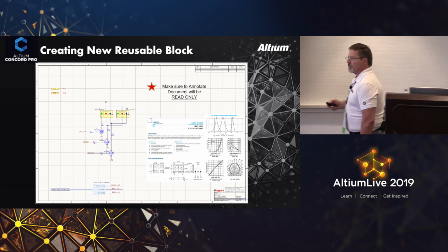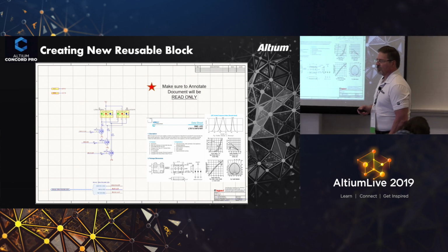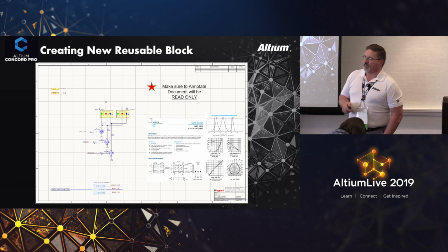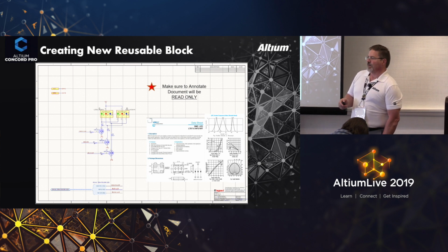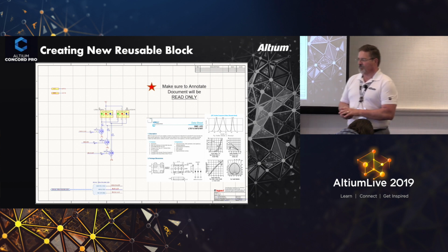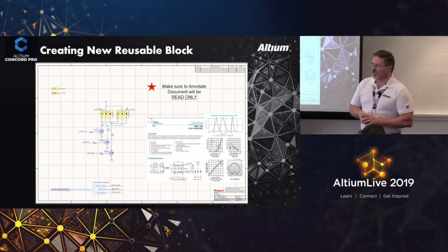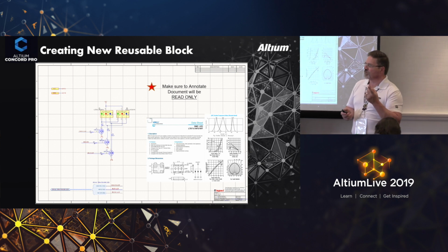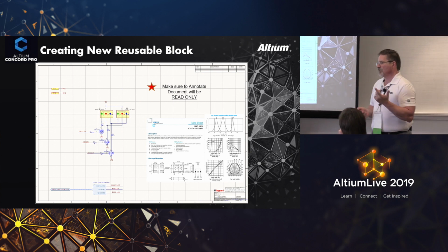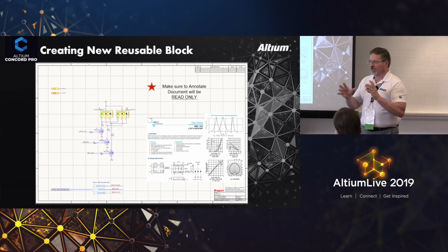So is this the idea here then, to have a specific PCB layout that you can also have a block for? And that's where there is a way around, yes, there is a way for that. But that's what the idea here is, as opposed to just grabbing the circuit from some other schematic and copying and pasting. I wouldn't copy and paste it from another schematic. First finding it, different things like that. Having different net names for your inputs, especially if you've maintained your input naming conventions, different things like that. It gets a little hairy when you're simply taking an old schematic and bringing it in.